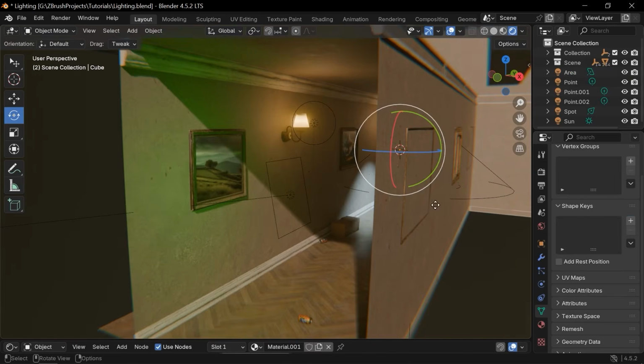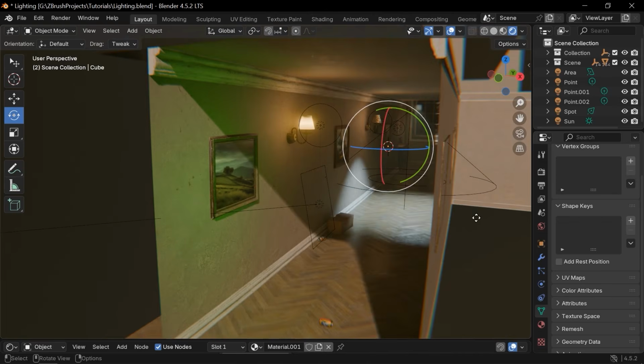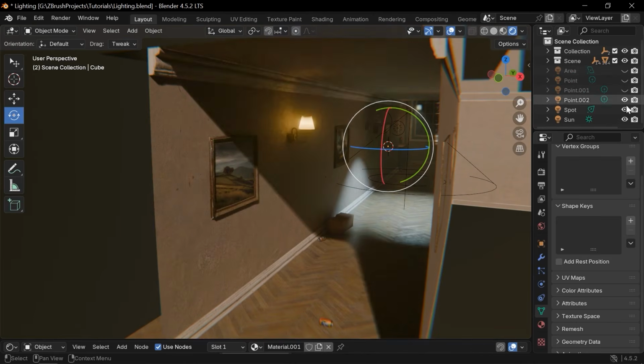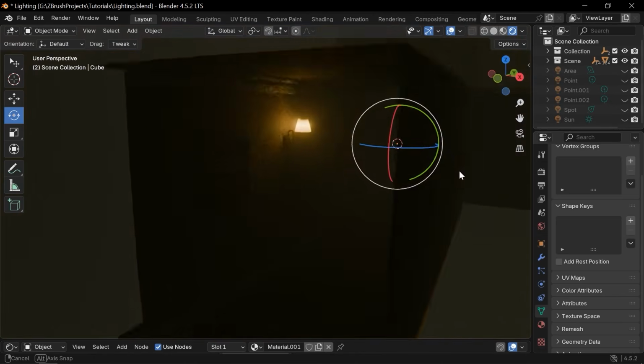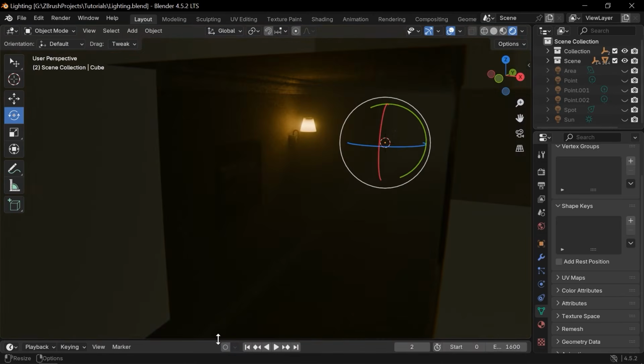Alright, these are the physical lights. Physical lights means they work with algorithms and some complicated calculations written by Blender, and they are so heavy to compute. But we have another light in Blender. Let's delete these lights or disable this icon, and now we can't see them. We have another lighting system called HDR. It's not physical, it doesn't have a complicated calculation. It will use a texture or an image to provide lighting.